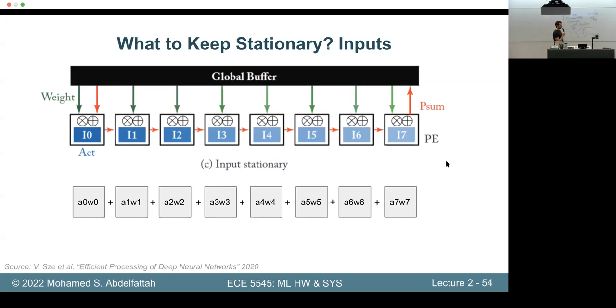I would say just in linear layers, right? You have your input, and you usually need to multiply it by different weights. So at batch one, fully connected layer, you would actually reuse your input across all of those weights. Because remember, it's a matrix vector multiplication where each row of that weight tensor is multiplied by your activation vector. So for a batch one fully connected layer, it might be really useful to have your activation cached on chip. But the answers are actually very creative and relevant.